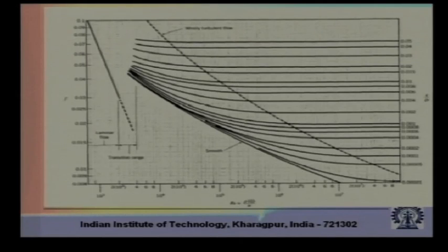So that is plotted on the right hand side. All the values you see there are epsilon by d. So where do you get epsilon by d from? If there is a manufacturer of a pipe, then depending on the material and the manufacturing process, the manufacturer has a code for the epsilon by d. So for a given pipe, you know what epsilon by d is. Of course, with wear and tear that may change, but at least initially, whatever the manufacturer codes is a reliable one.